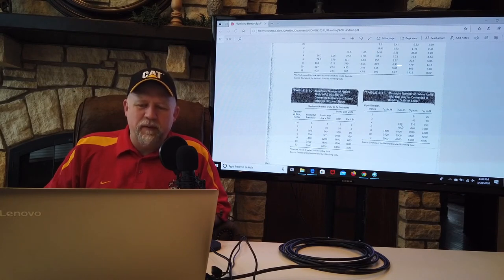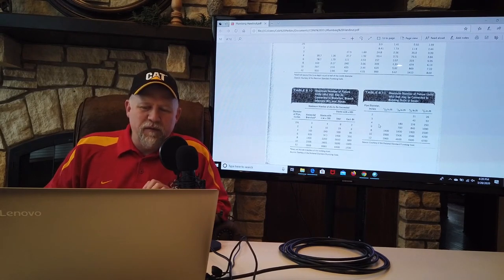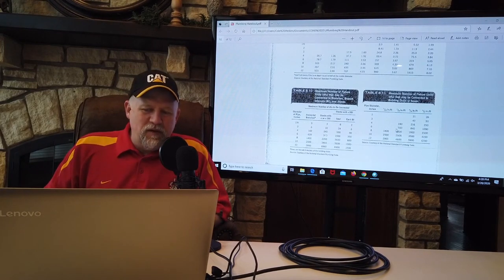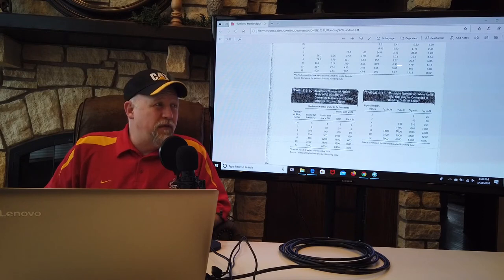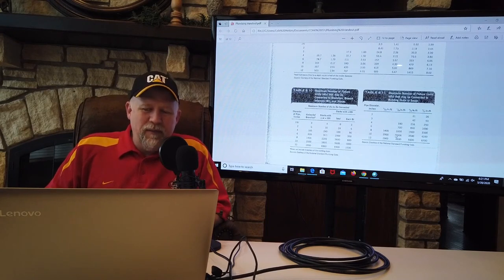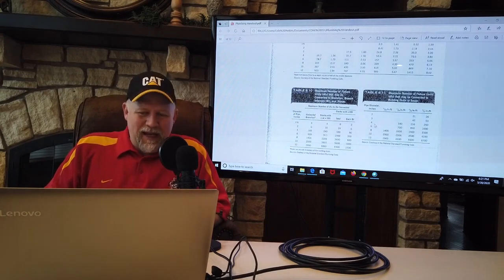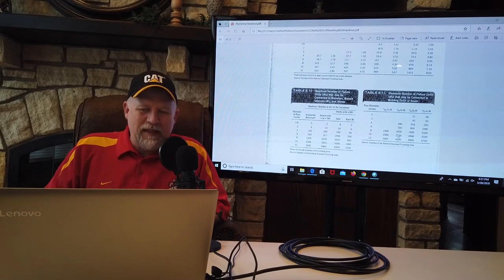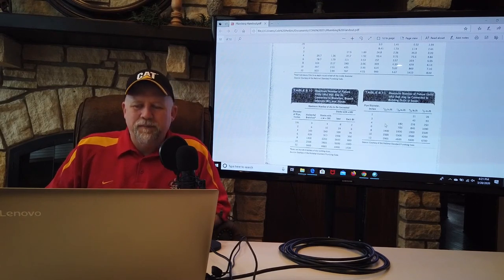And that's only for sewers 4 inches and above. But in all honesty, for a building main drain, there's no point in making one less than 4 inches because most toilet outlets are also 4 inches. Just as a friendly piece of advice, do not size a sanitary drain pipe from a toilet at less than 4 inches.